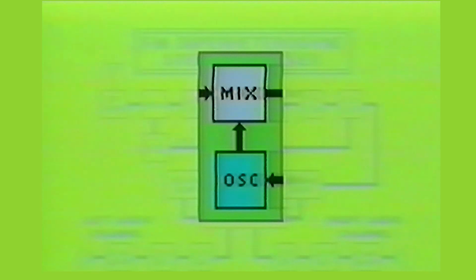At this point, the mixer stage will heterodyne the two signals and produce the sum and difference of the frequencies which contain the modulated information. This new intermediate frequency is then fed into the first IF amplifier stage.